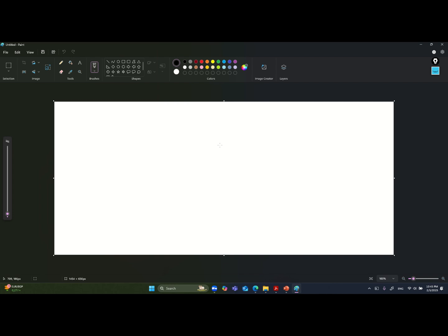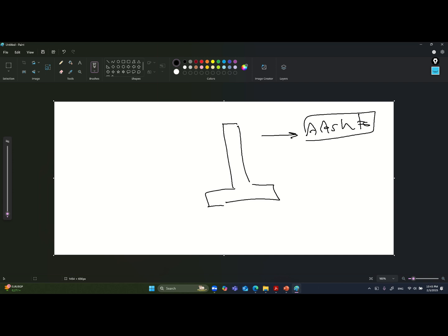So if in the exam he mentions that you have a retaining wall, of course anyone who hears about a retaining wall will run to ASCE. That is one of the tips and tricks of the exam. He mentions a retaining wall, but he will not give you enough information, like the friction angle. He will give you the backfill material, like GW, and he tells you what the overturning or the maximum moment is here.